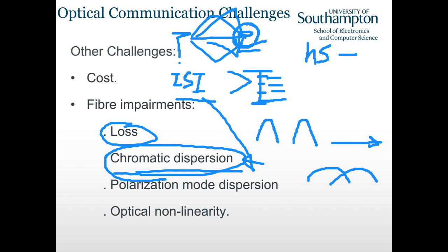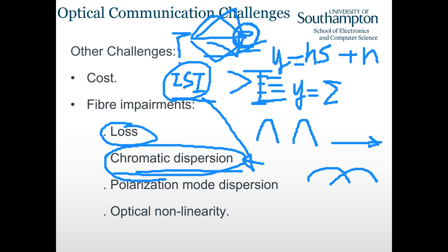And then we receive one symbol. There's basically no inter-symbol interference. However, if I have multiple copies with different delays for RF, and then for optical, we have different wavelengths, they travel with different speed, so they arrive at a receiver with different delays. So what we have is we receive a symbol, which is the summation of all the delayed signals with their fading element. So this would introduce inter-symbol interference.